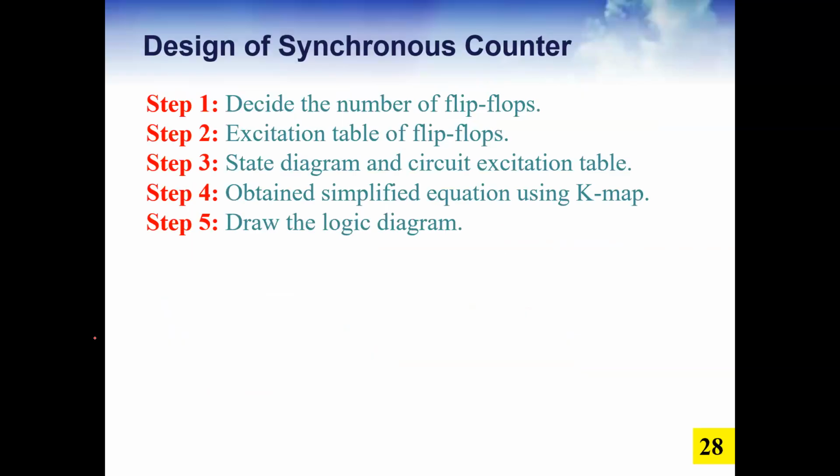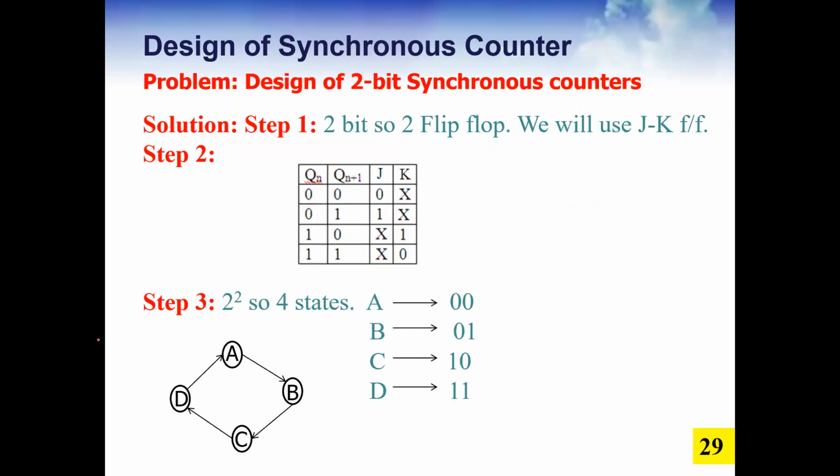So again, first of all, you need to decide the number of flip-flops you need to design. Then you need the excitation table. Then you will have a state diagram. From that state diagram, you need to use the K-map and find the equations. And then finally, you will draw the circuit for the counter. So let's see this one.